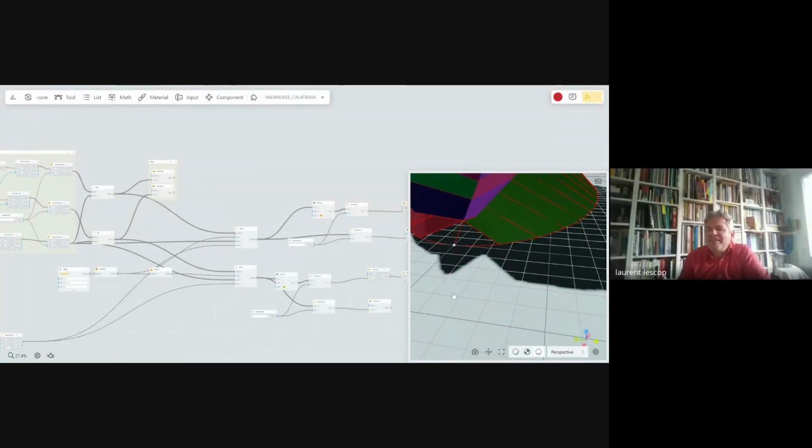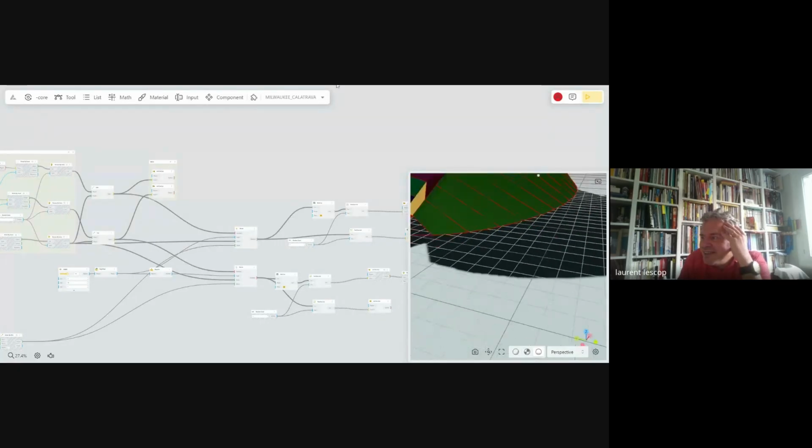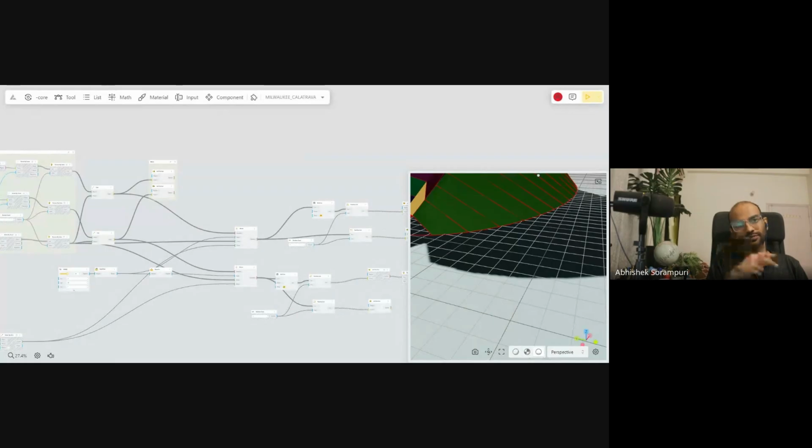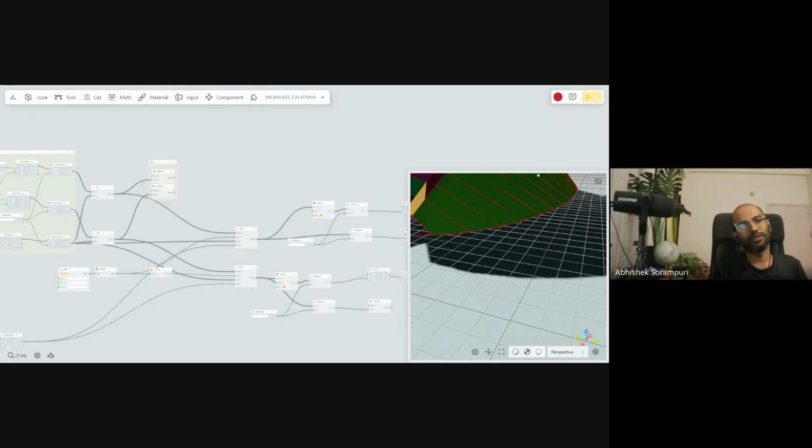What do you think of it? Trying to fill this gap, I think there are many possibilities, but I've got to figure out the best way and the easiest way to do that. I was checking initially splitting the curve, at the end and in the beginning as well. If you split the curve, have two separate curves, and then loft from there, that would have worked better instead of having one single ellipse. Yeah, you're right.